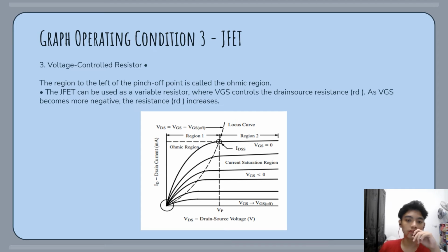Voltage control resistor (VCR) may be defined as a 3-terminal variable resistor where the resistance value between two of the terminals is controlled by a voltage potential applied to the third. For a junction field effect transistor (JFET), under certain operating conditions, the resistance of the drain-source channel is a function of the gate-source voltage alone, and the JFET will behave as an almost pure ohmic resistor.